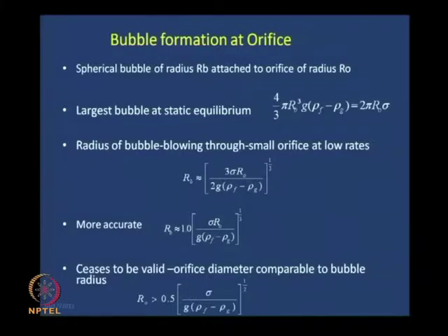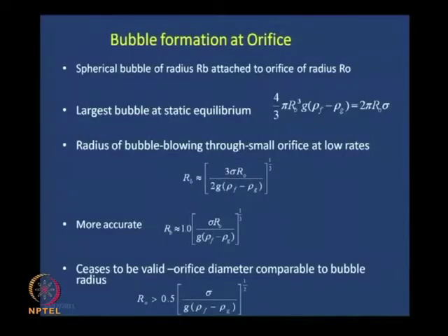Now, the size of the bubble depends upon how the bubbles have been generated. The different ways of bubble generation and the size which we get as a result, I have also noted down because they simply comprise some particular equations. Equations come from force balances, some of the equations are empirical equations, but all of them are available in standard textbooks, so you need not take them down. But I will just be discussing the different methods of bubble formation and how the bubble size is determined for the different methods. For example, the most common technique is bubble formation at the orifice.